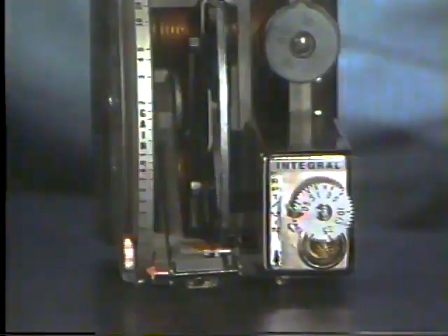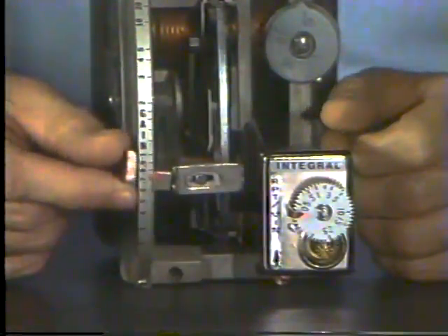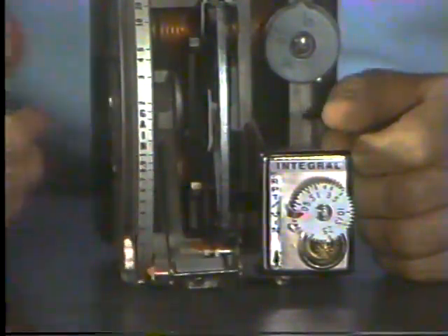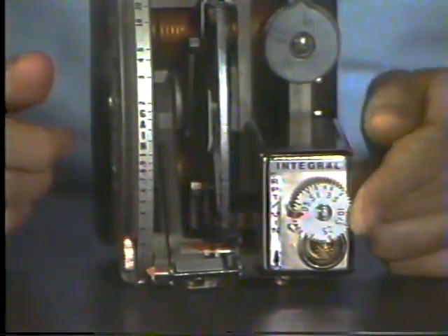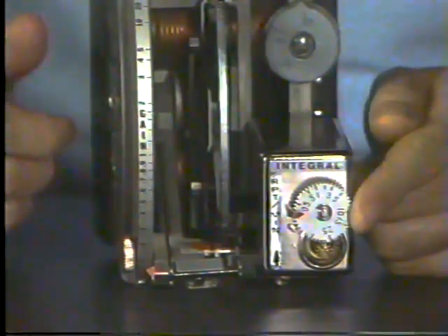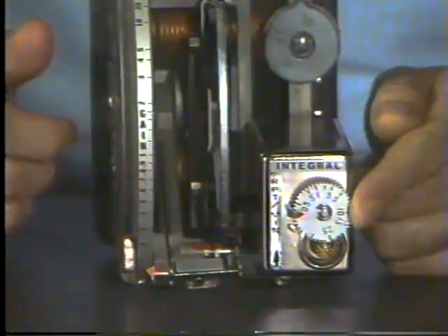When you tune a control system, the specific adjustments you'll make depend on the type of controller and the process being controlled. For example, this PI controller provides both proportional and integral action. When tuning it, you have to make at least two separate adjustments. A gain adjustment to set the proportional response of the controller, and a reset adjustment to set the controller's integral response.